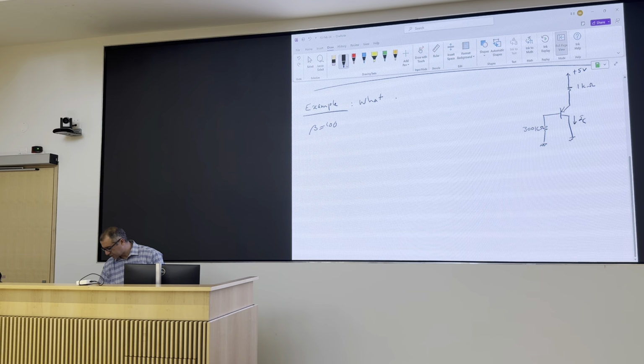Second thing, base current usually goes up quite a bit. So you design the circuit for 10 microamps of current, all of a sudden you notice maybe hundreds of microamps or milliamps are going into your base. If you're measuring two currents, the ratio of IC to IB usually becomes worse. If you're making an amplifier with this circuit, usually your gain drops when it enters saturation, right? Or it's getting close to saturation.